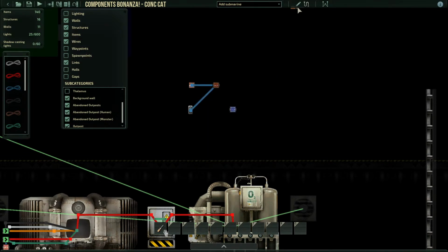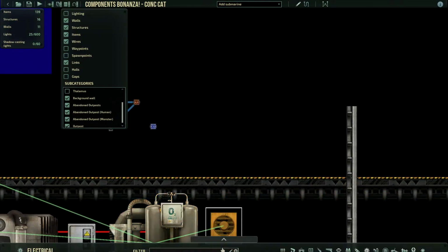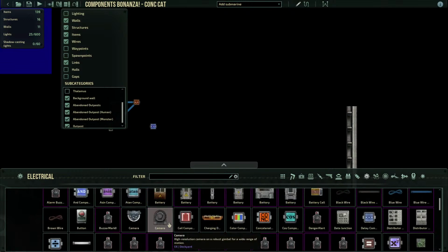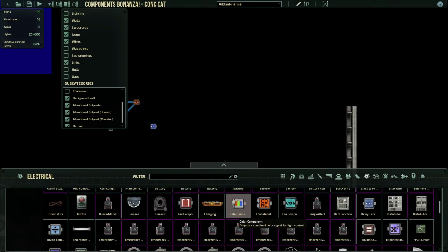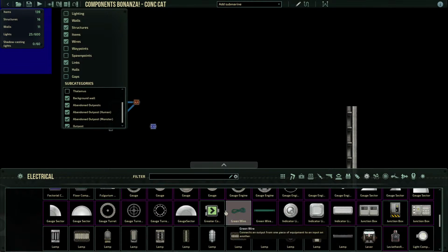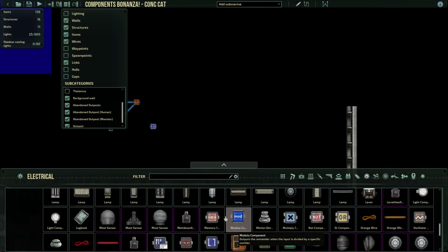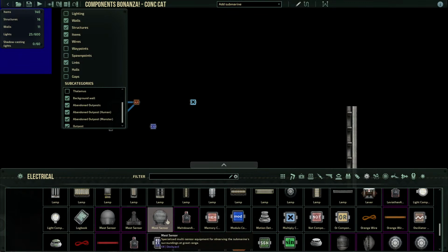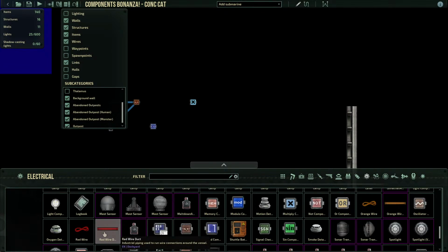Okay, now I'm going to add a bunch of blocks over here. They're not entirely necessary, but what happened earlier was that I tried to display the output from the oscillator, and the oscillator was using a sine wave that was going from 0 to 1, but you couldn't read it on the text display. The reason that happened is because the text display was trying to update like 12 decimal points at the same time. And by the time it was done updating, another calculation had been done.